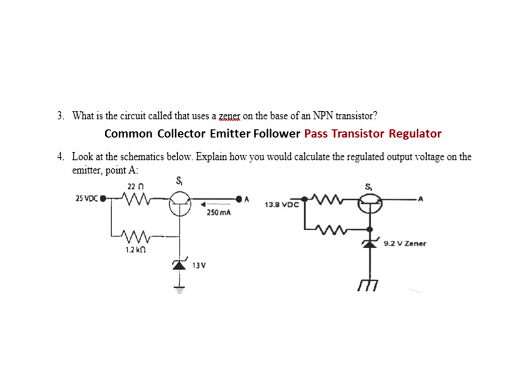Here's how it works one more time. First of all, it's not going to be 13 volts out. Although zeners do conduct to limit their voltage to the zener voltage across the terminals, I set the voltage right here to be 13 volts for the zener, and then I'm going to lose 0.7 volts here. So 13, the zener voltage, minus 0.7 base emitter, gives me 12.3 right there.